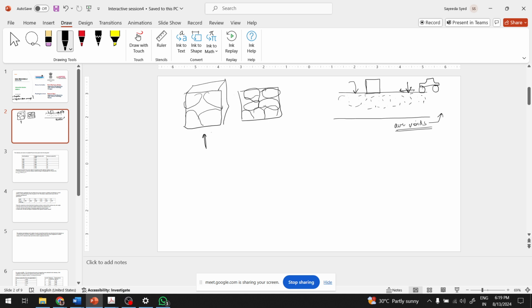In this unit volume, you can see you have a lesser amount of solid material and more voids here, and lesser voids here. So the unit weight gamma dry, because we're talking about the dry state of the soil, will increase as the compaction proceeds. So what we want to do is increase the gamma dry of the soil by compaction.